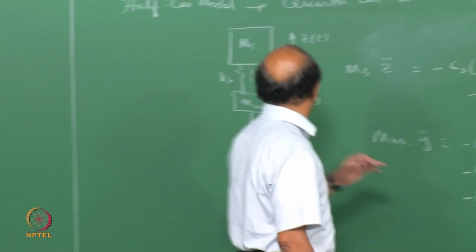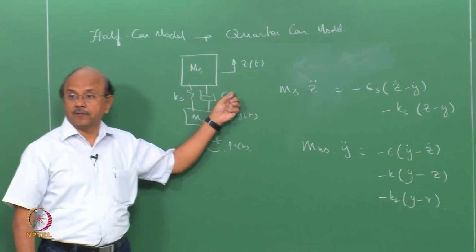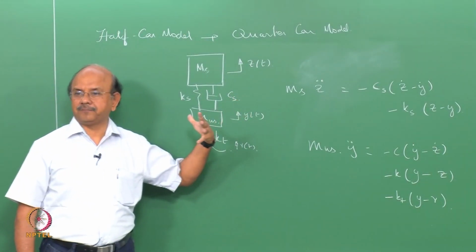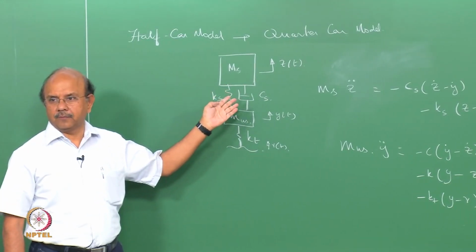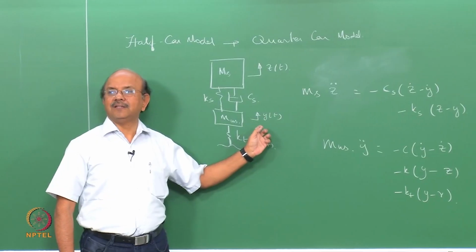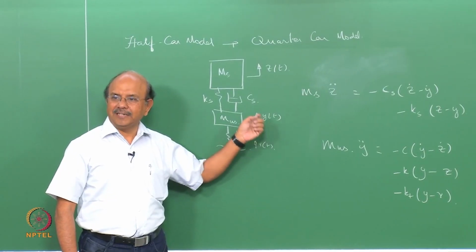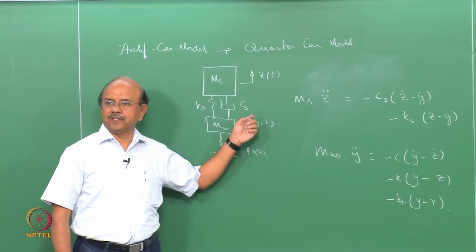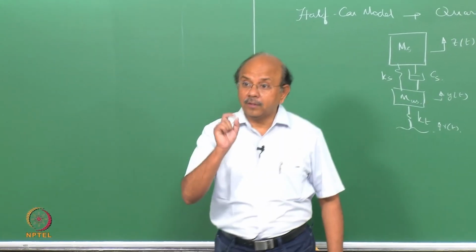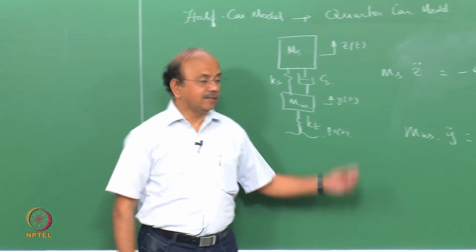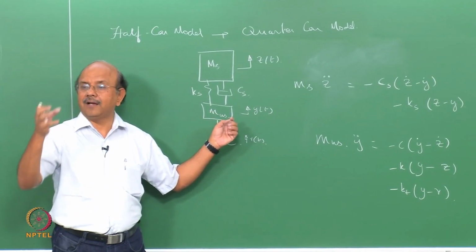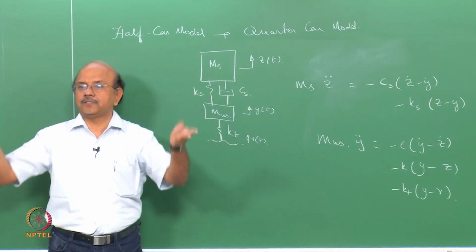The more important damping is the shock absorber. Does it mean that the shock absorber does not have any effect when I remove it? Fortunately, the difference between the natural frequencies of an undamped system and the damped system is very, very small. Though in the whole of mechanical engineering this system is one of the very highly damped, within quotes, it is an underdamped system.